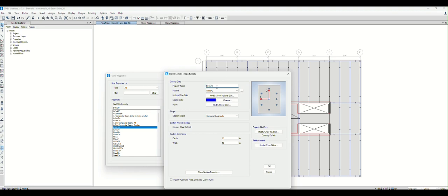This beam, especially, we call it a link beam. So we have an 18-inch thick wall, right? For depth, we're going to just assume all 24 inches. And for concrete strength, with wall thickness 18 we're using C5. So width is 18, depth is 24, right?